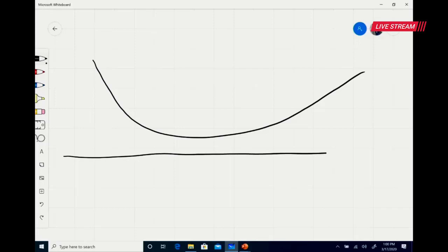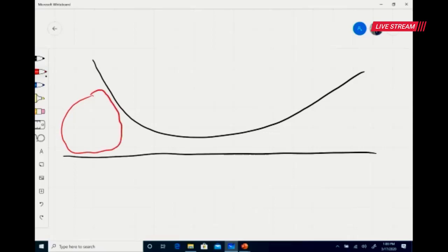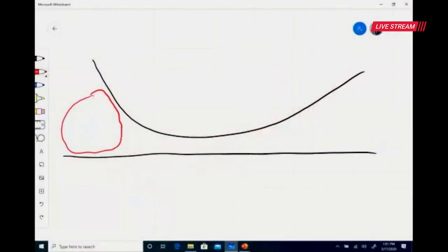And this bearing's rolling around the race, and we've got a particle. And this particle is very large, all right? Let's say that this is around a 40 micron particle or something. The size may be such that it's so big that this bearing is just going to push this particle along, or it's not going to allow it to actually get in the fluid. Now, over time, this particle gets captured, right? It gets pressed on or something like that, and we start to crack this particle, right? It starts to break down.